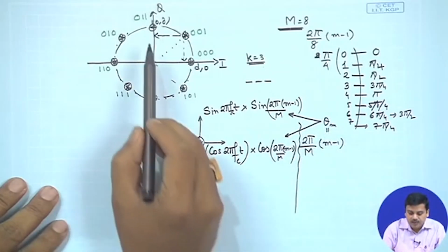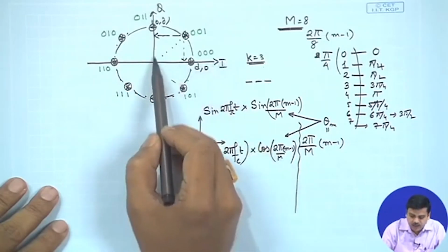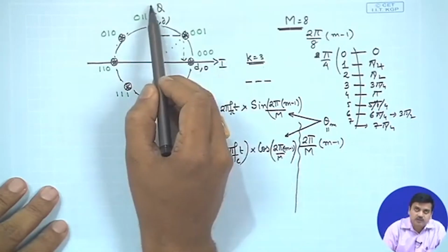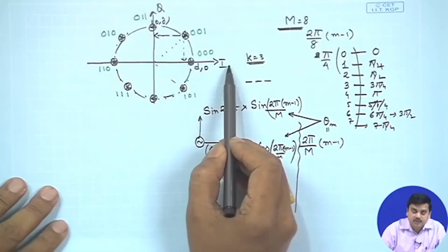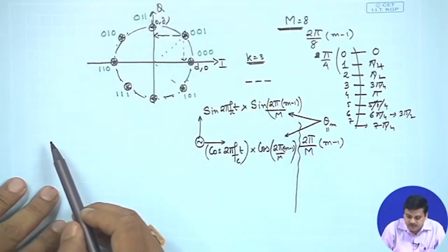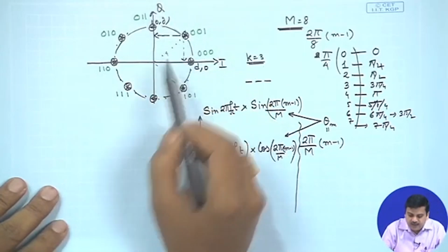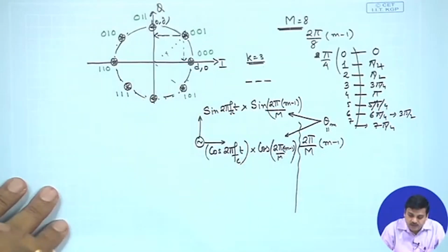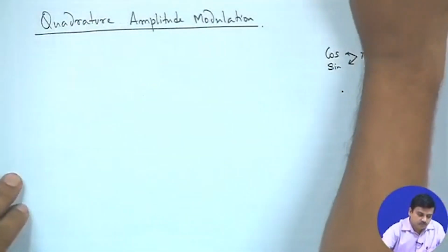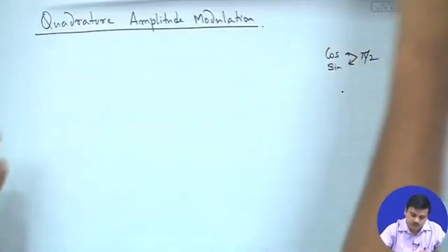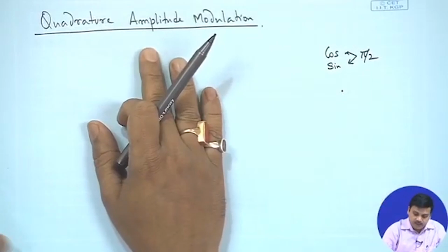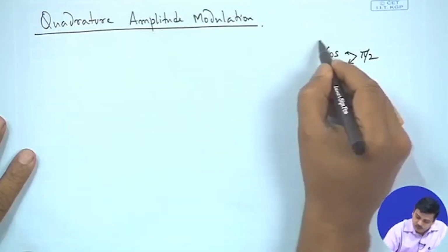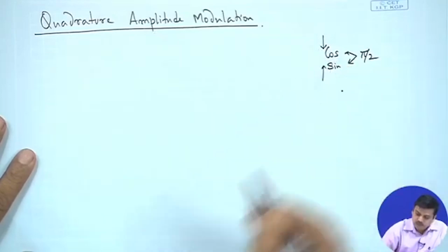That means the amplitude of the I component, the in phase, and the quadrature phase component. So, if we call cosine the in phase, then sine is the quadrature phase. They are dependent only on the angle and nothing else, right. Whereas, if we talk about quadrature amplitude modulation, here we are talking about modulating the amplitudes through independent data streams, which is quite in contrast with what we have studied before.